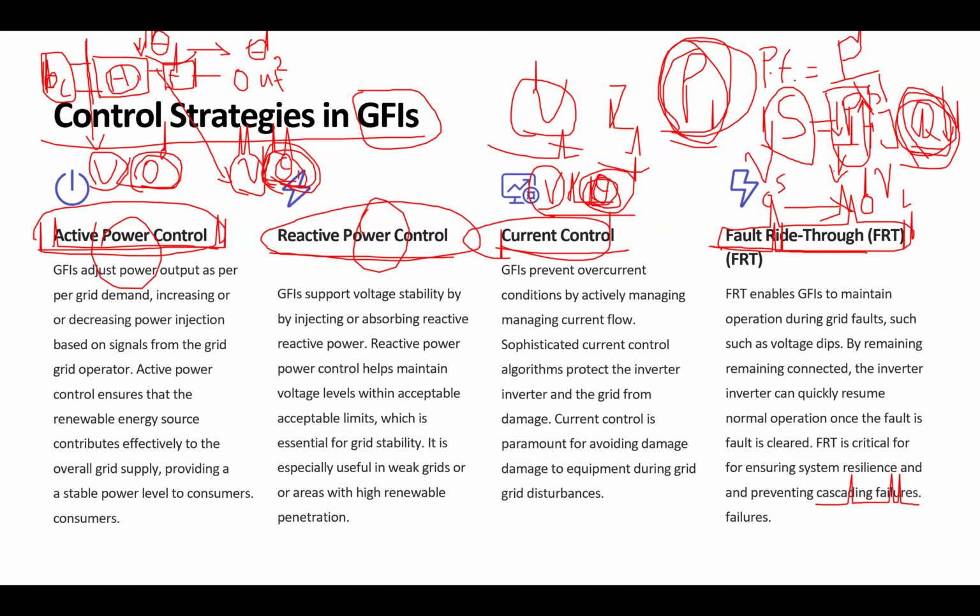You mean when the motor starts, there is a surge of current from the grid, right? And you wanted to see how this is considered as a fault. This is not considered a fault. The surge of the current is going to have a flicker effect on the voltage in the power system, but that surge of the current, the starting current of the motor, is not considered as a fault.